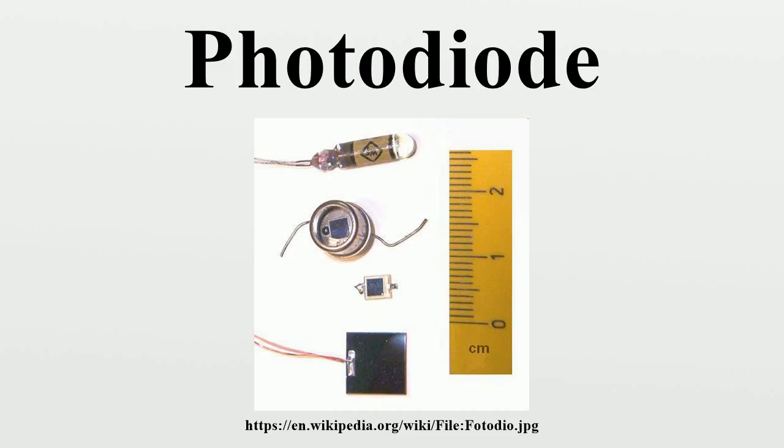The resistance and capacitance of the photodiode and the external circuitry give rise to another response time known as RC time constant. This combination of R and C integrates the photoresponse over time and thus lengthens the impulse response of the photodiode. When used in an optical communication system, the response time determines the bandwidth available for signal modulation and thus data transmission.